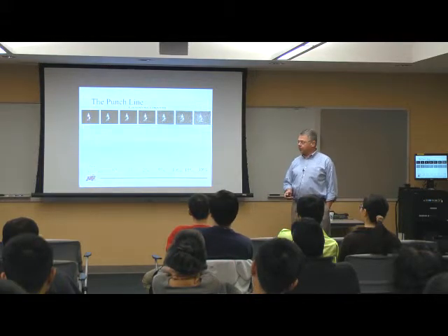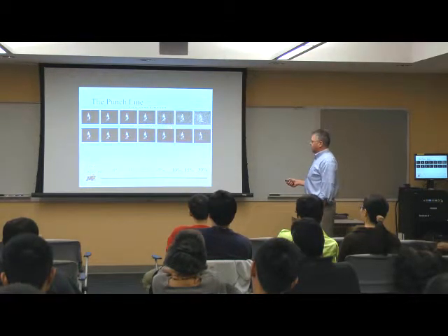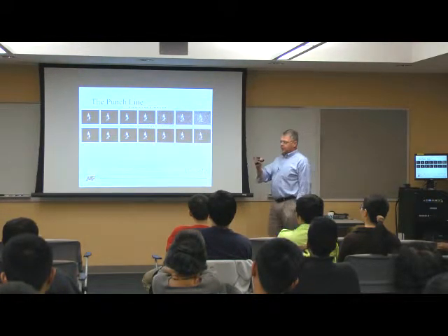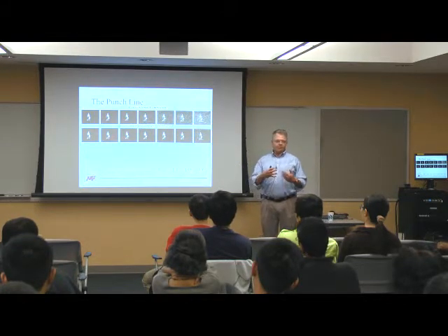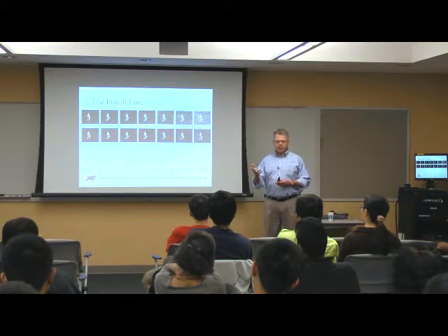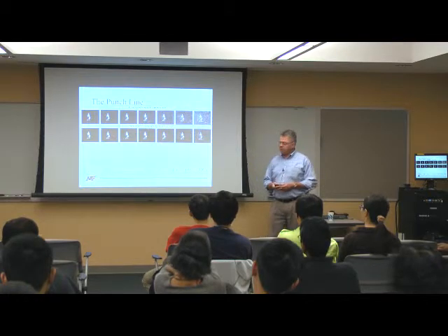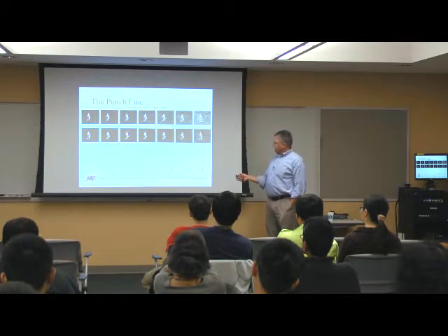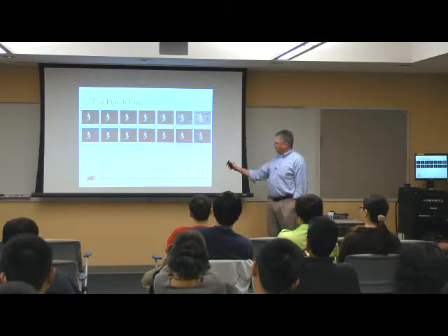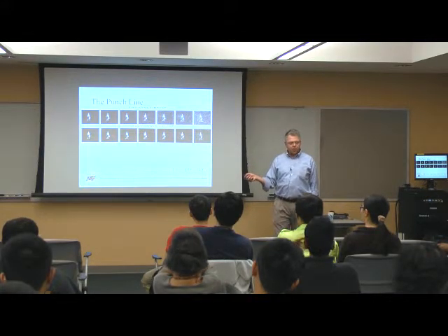Traditional approach for tolerating this would be something like triple modular redundancy. So I duplicate the circuit 3 times, I compare, and I take the best 2 out of 3 and say, okay, that's the correct result. If I do that, I see the same pattern developing here, but it's just shifted. So I can tolerate more errors.